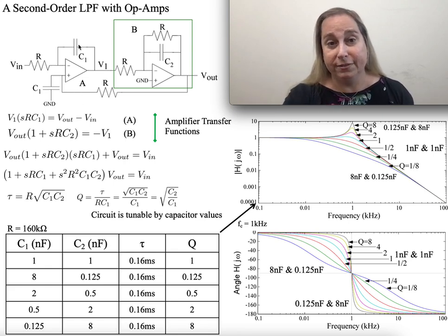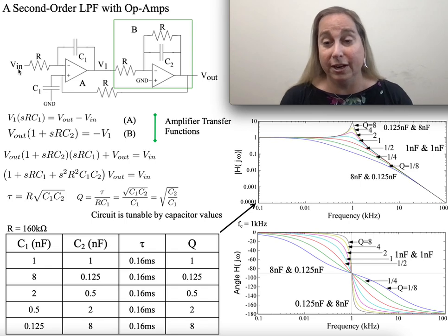And then I have an amplifier in a differential configuration. So you'll notice that I have both R and R coming into the plus and minus terminals, and then in the feedback and to ground is the C1 terminal. This is what you would expect in terms of getting a difference configuration between the output voltage under the plus terminal and the input voltage onto the minus terminal. And so what's nice about it is these are first order structures.